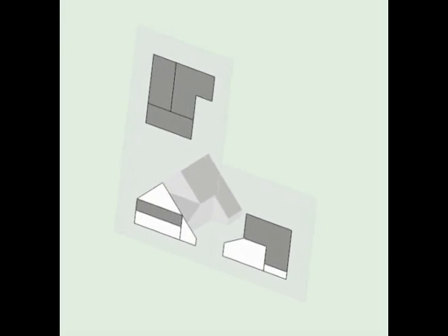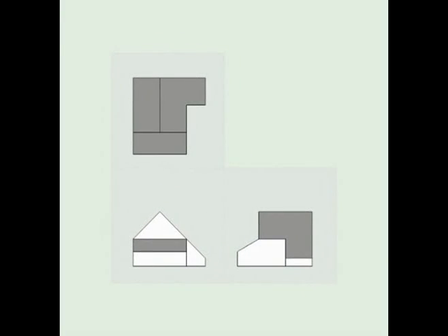To establish the proper relationship of the three orthographic projections, we unfold the picture plane box into a single plane. The result is a coherent set of orthographic views. Align related orthographic views so that points can be transferred easily from one view to the next. Project points to adjacent views using projectors that are perpendicular to the common fold line.